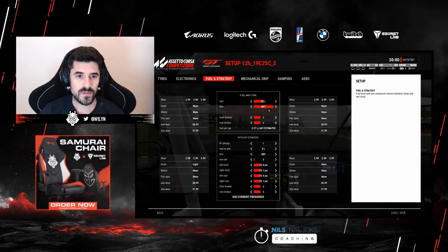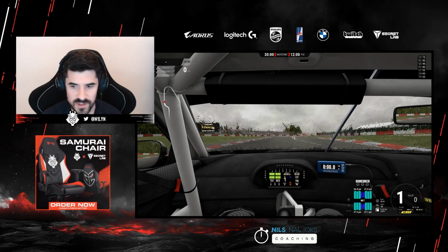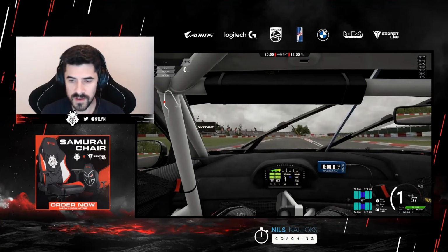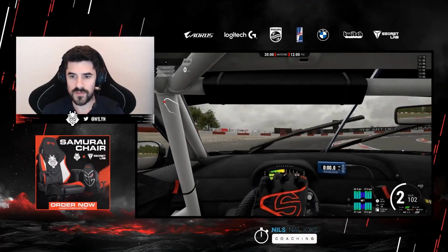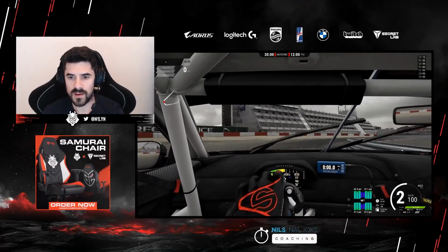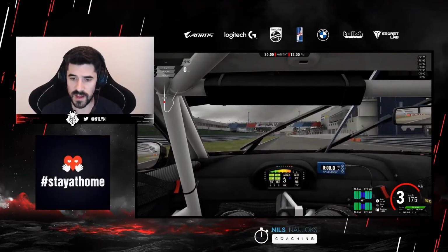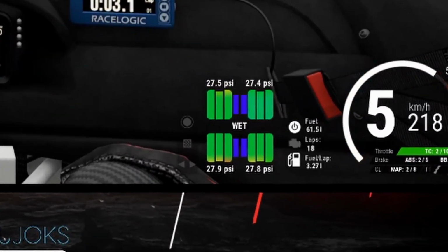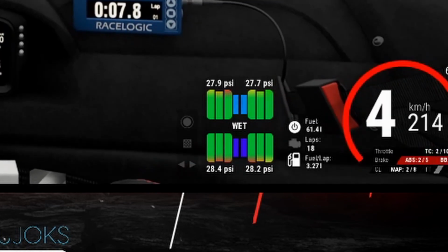So I'm taking it to the track now with a wet tire in greasy conditions, which means it's a tiny bit wet, it just started raining on the optimal surface. The rain tire very likely is going to be way too soft for these conditions. It's not wet enough yet for this tire to work. And already now you can see it if you look at the tire wrap below, just by going straight with rain tires in these kind of damp conditions, they will heat up a lot.